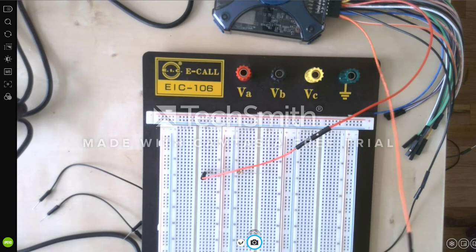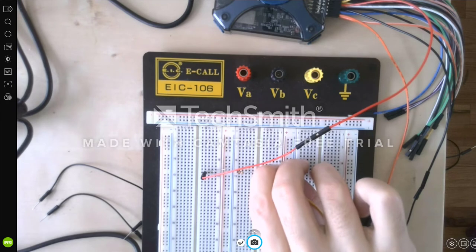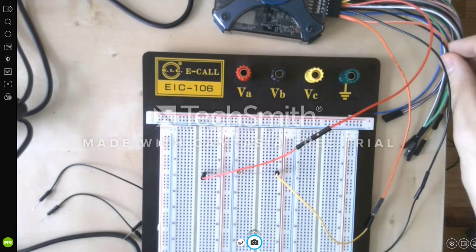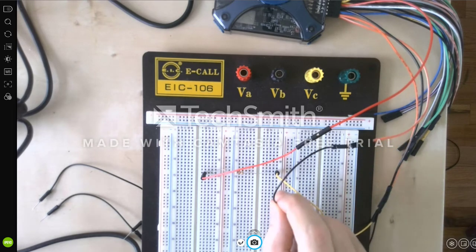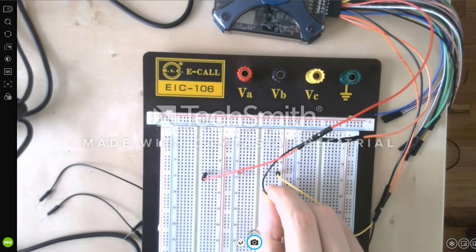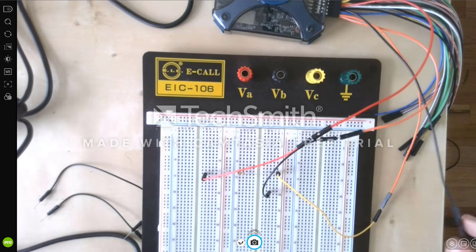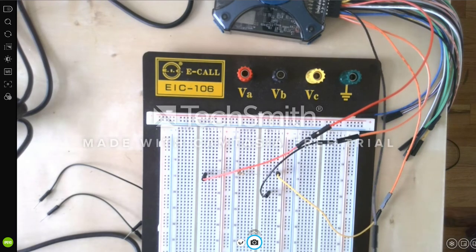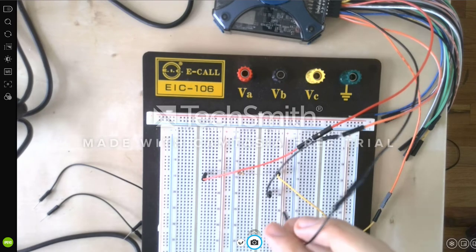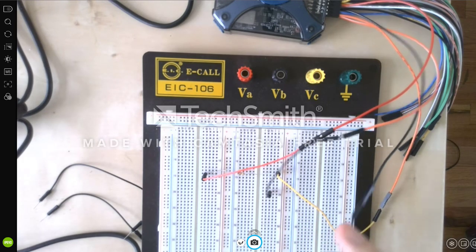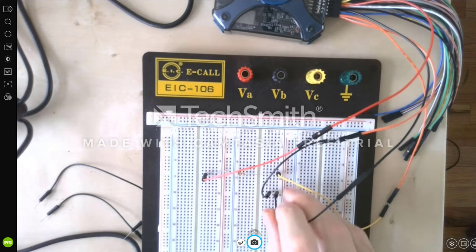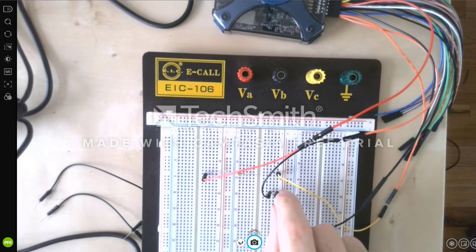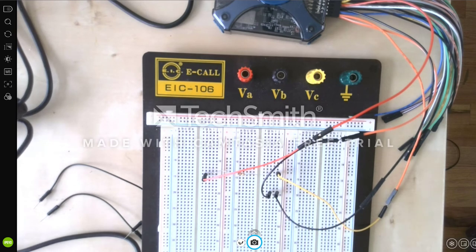We are plugging in the first cable from the left, which is the first channel, and we are plugging its negative pole in and grounding it. Remember that we should always include a ground on our breadboard. All right, the first circuit is ready.